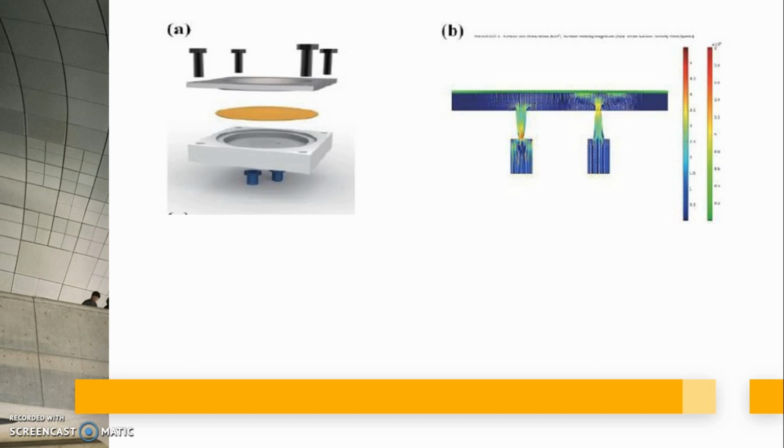The velocity of the fluid increases along the nozzle section and reaches its largest value at the end of the nozzle. Due to the diffuser angle, which equals 180 degrees, it locates in the jet flow region, and the high velocity fluid generates turbulence in this region.